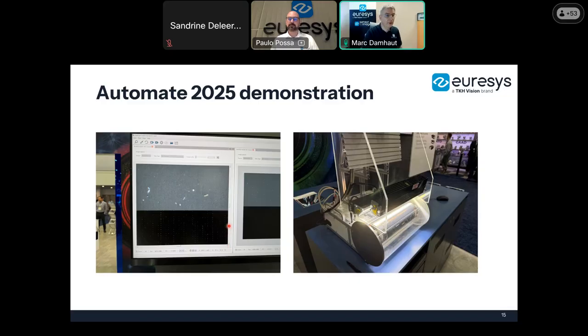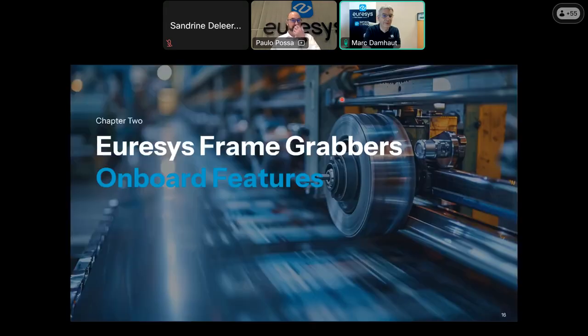And this is all done by the frame grabber during the acquisition, using what we call DMA de-Interlacing or DMA de-Interleaving. That's a function which does not take any CPU, so it's completely free to execute during the acquisition. That was actually a good example of the new feature that we have added in one of the latest versions of eGrabber.